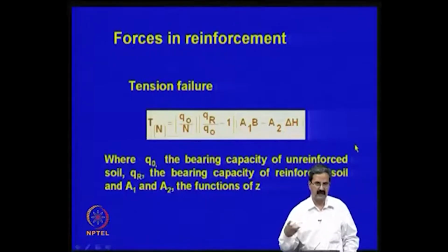It is actually a theoretically derived expression, because it essentially involves elastic stress distribution. A1, A2 are constants, one can get them from these plots, and N is the number of layers, QR is the required bearing capacity, Q naught is the original bearing capacity, B is the width of the foundation, and delta H is the spacing of the reinforcement elements.